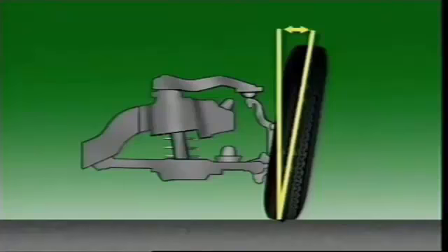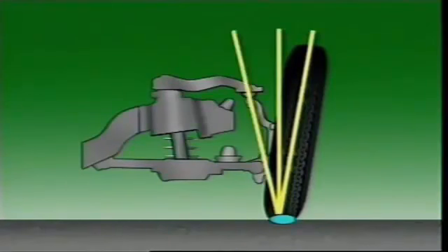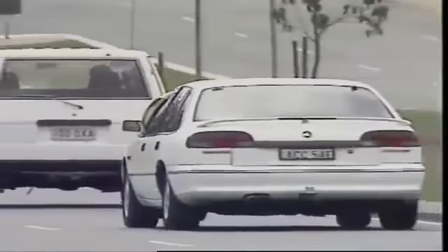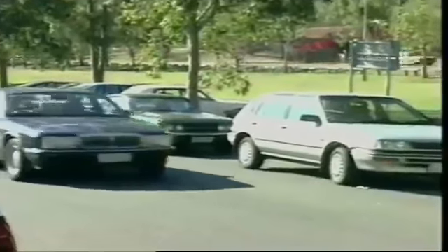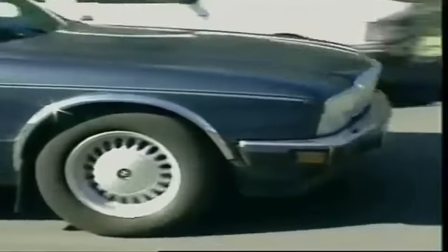On earlier vehicles with narrow tires with a large diameter, large camber angles were used to bring the center line of tire road contact closer to the steering axis. It also ensured the vehicle weight was carried by the large inner bearing. On modern vehicles, however, tires are wider, but they are generally smaller in diameter, and large camber angles would produce excessive wear on the outer edges of the tires.